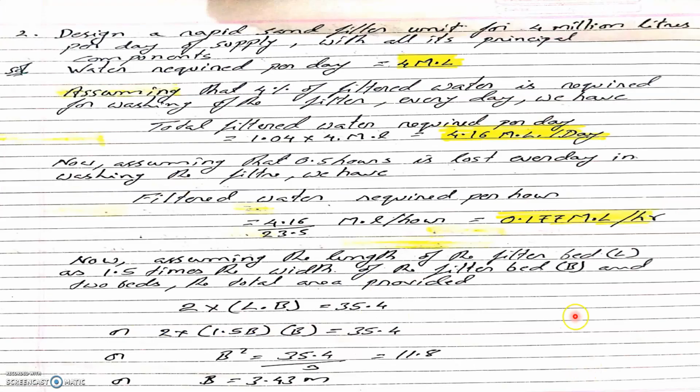We are going for another set of problem over here. What he has stated here is: design a rapid sand filter unit for 4 million liters per day of supply with all its principal components. What he has given is 4 million liters. Here we are assuming that 4% of the water may be required for backwashing. So considering that, for the calculation part, total water required per day